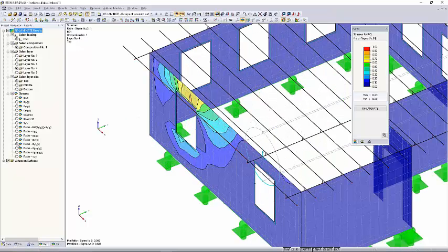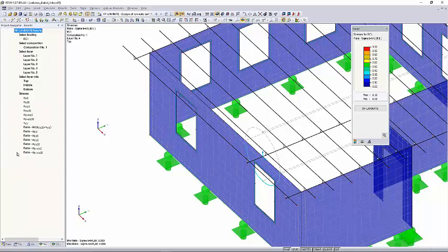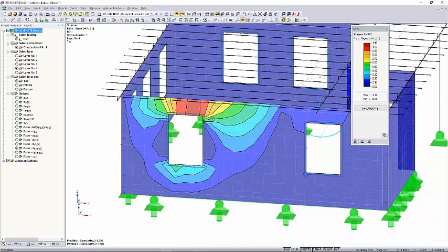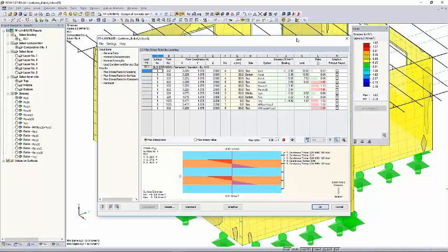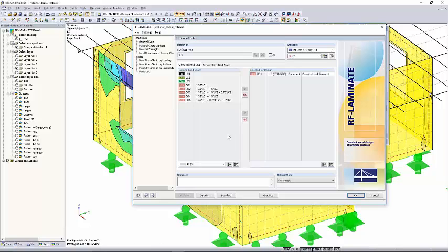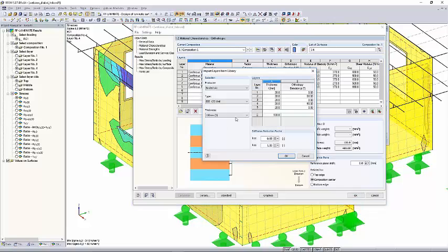So that's probably because of the high wind we have in England, because it gets a lot of bending in there. So that's actually not a singularity point. That's something where you would need a thicker wall. And you can see that I'm not often designing in the UK with high wind loads, better say.